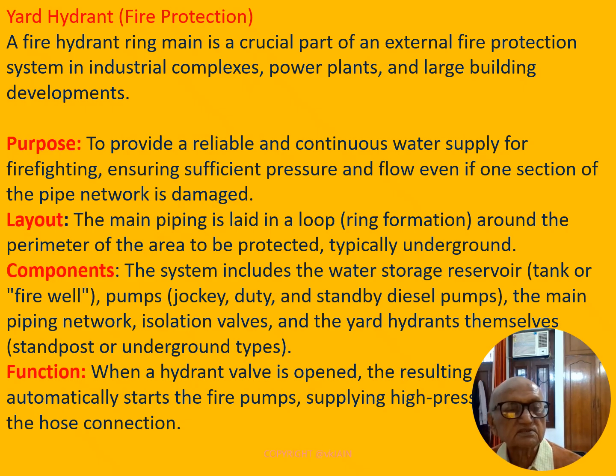The purpose is to provide a reliable and continuous water supply for firefighting, ensuring sufficient pressure and flow even if one section of the pipe network is damaged. It is designed in a ringmain fashion, so water can go in either direction.